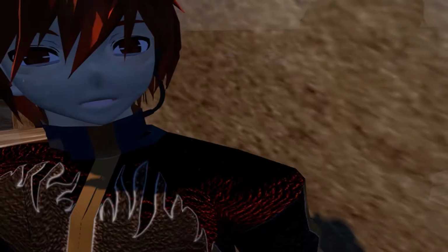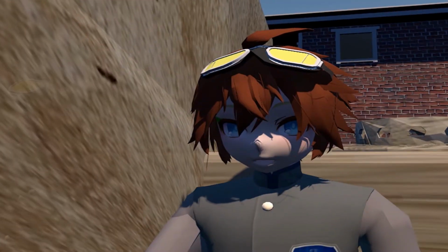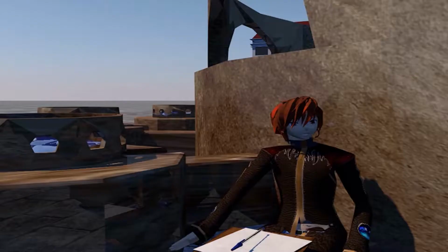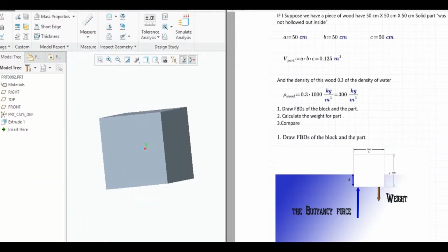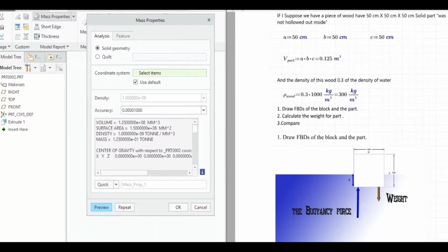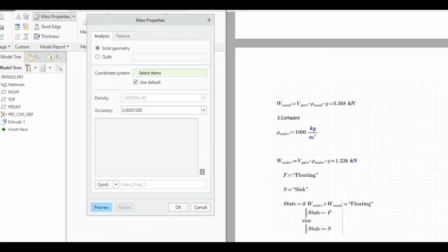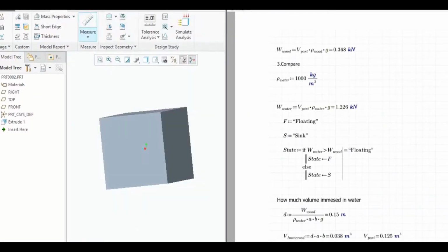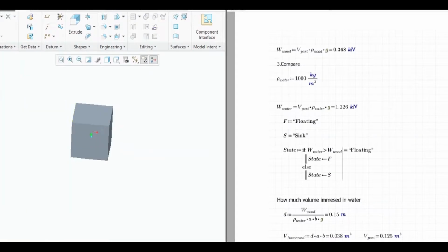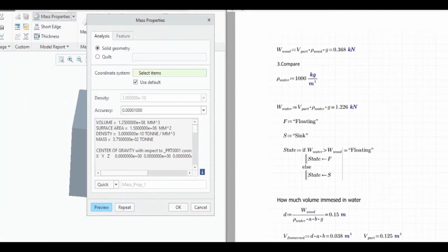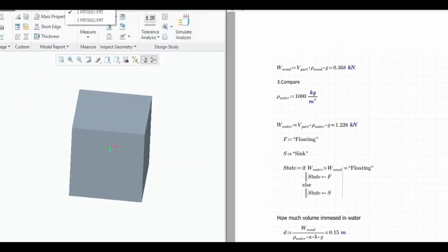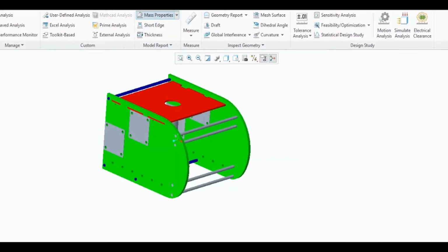How can we calculate buoyancy force for complex shapes and different materials? For a complex shape, or something we need to optimize, we use a CAD program and an analysis program. I will show you an example. Look, I will show you the same part we calculated, in CAD. We only need to run an analysis to know the volume, density, center of gravity and center of buoyancy. This is another example, for an ROV. You can calculate buoyancy force for a lot of things.